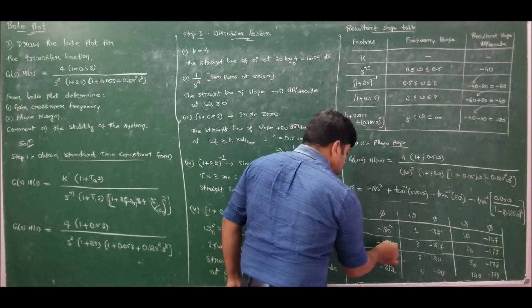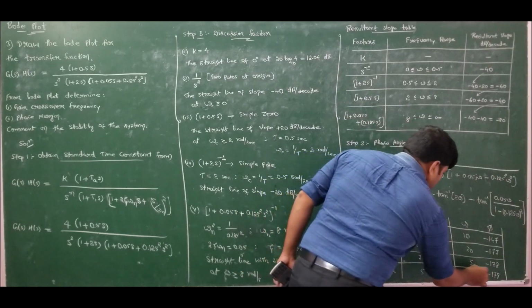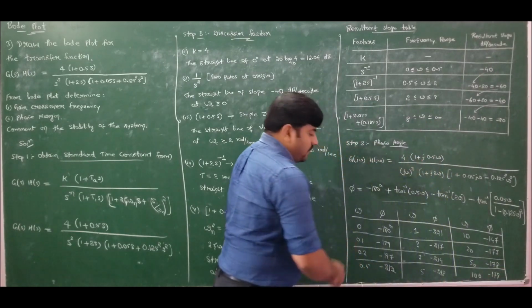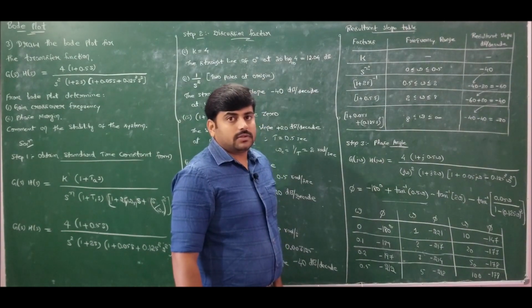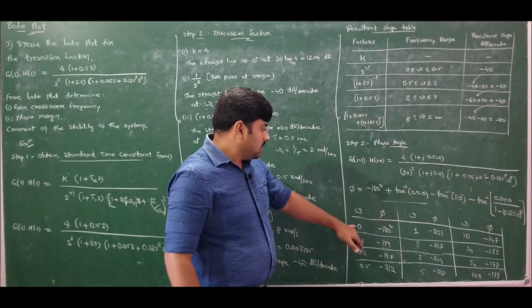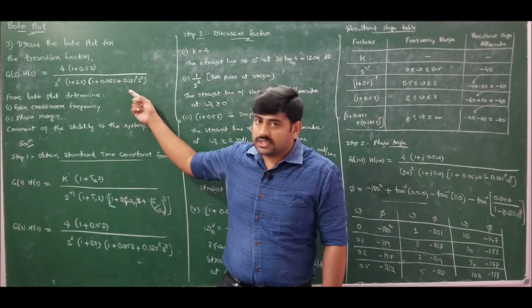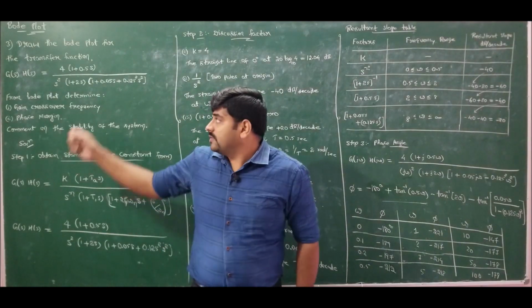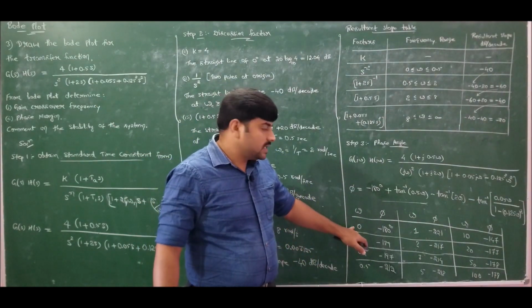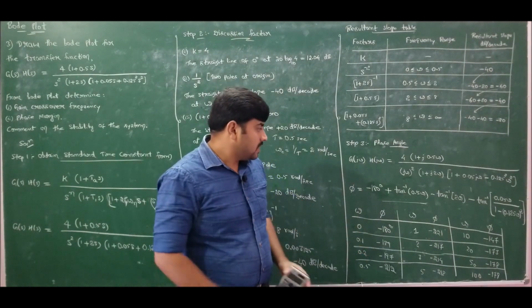It is the inverse of the magnitude evaluated at the phase crossover frequency. That is minus 20 log 10 of the magnitude evaluated at omega equal to 0. So I should determine the magnitude of the given function and find the value of minus 20 log 10 of this magnitude, evaluated at 0 radians per second. That will give us the gain margin.